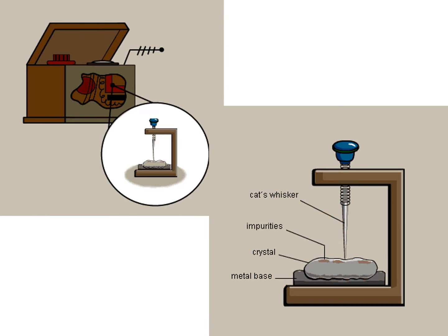These are the first radios. This is around the turn of the century, the turn of the 19th to 20th century, about 1902. They're called crystal sets, and they consisted of a crystal of a mineral called galena. Here's the crystal, and what's called a cat's whisker. That's this little wire right here. Here's the handle so you can control the wire. By moving the whisker around on the crystal, the station would come in clear.